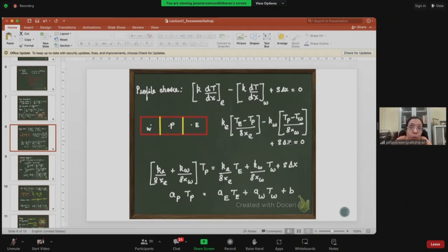So while you're running the solver, I want you to look at the FE schemes folder, and look at what is the scheme that is being used there. Then we will briefly discuss what it means. So with this background, that you're going to be doing a conduction equation solution using the Laplacian solver, I would like to get into the work of actually setting it up.